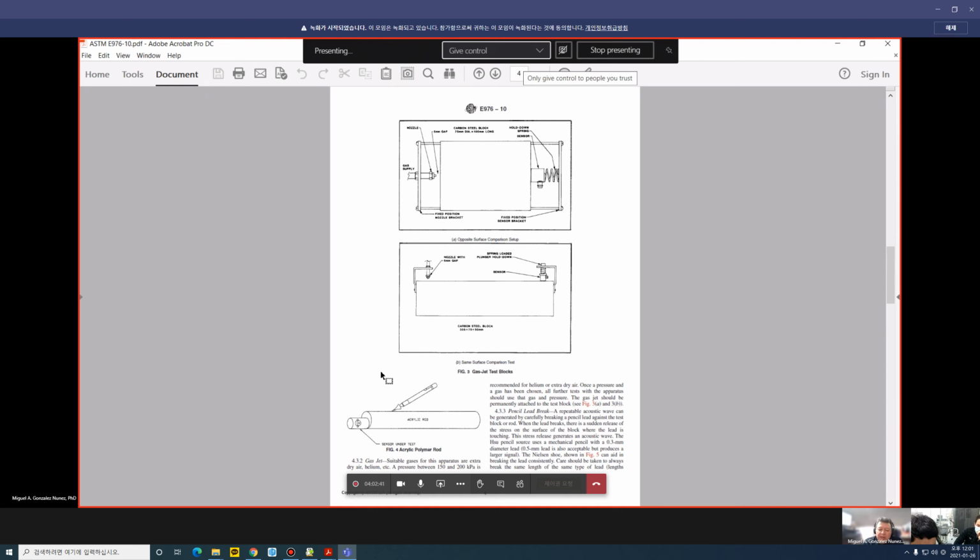Then you do the same thing on your test specimen, now with the sensor mounted on the test specimen with dry coupling, and perform 3 pencil breaks 5 centimeters away from the sensor. And then you compare those readings with the reading that you did on the acrylic.